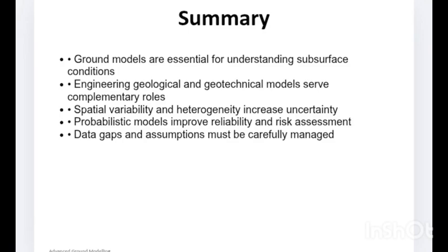Data gaps and assumptions. Incomplete data require assumptions, but assumptions also introduce risk. And as a result, how do we manage this uncertainty? Additional investigations such as geophysics, sensitivity analysis, and observational methods help reduce uncertainty. So the key message here is this: the ground is inherently uncertain. The earth is variable, is heterogeneous. So a lot of uncertainty. And successful engineering depends on understanding and managing that uncertainty.